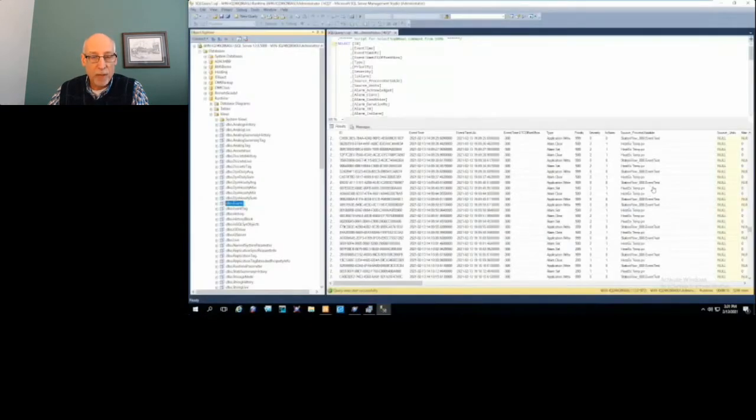The way we extract the information, if we go into the Historian runtime database, is we go into a view called the events view, and we query that data. So here's a query executing all the columns from that event view, and we give it a time frame, and you can see some of the data we've been playing with, some of the alarms we've been generating with our test scenarios.